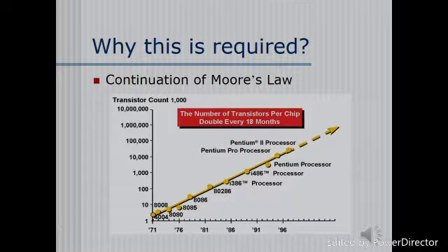In the mid-1990s, Intel came up with a solution. This can be achieved by changing the dielectric inside the transistor from silicon dioxide, which has a dielectric constant of 3.9, to something with a higher dielectric constant. Having a higher dielectric constant K provides more capacitance through the parallel plate capacitor and even increases the drive current through NMOS and PMOS transistors.